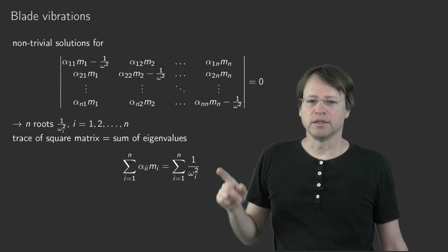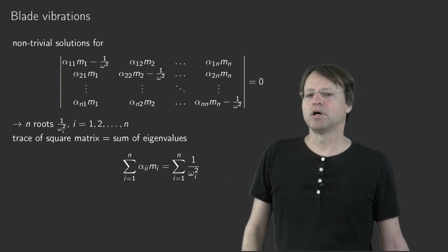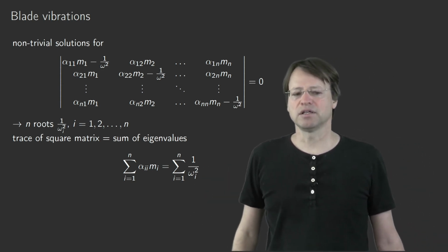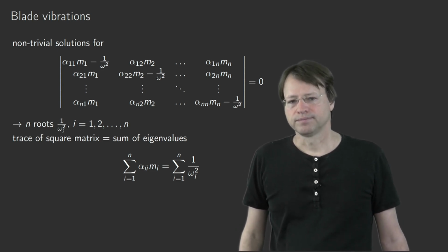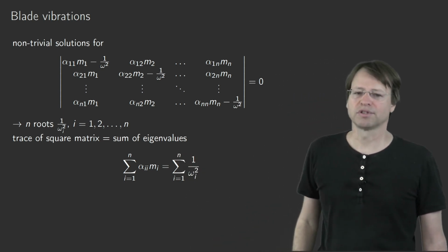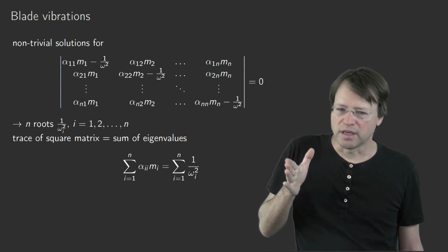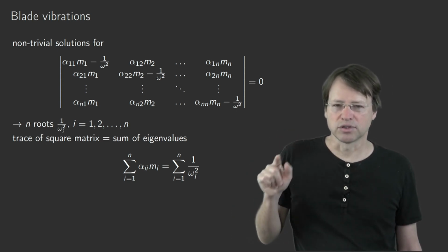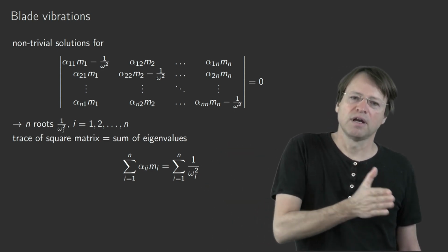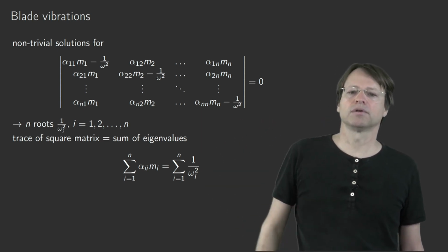Well, and this result now allows you to establish a lower bound for the natural frequencies, because the natural frequencies appear in the denominator. They appear all as positive quantities. Well, they are positive, of course, the natural frequencies, and they appear even in the square. You know that they are ordered. We ordered them starting with the smallest one, leading to the largest contribution here. And then we have higher natural frequencies, and the higher the natural frequency, the lower the contribution here.